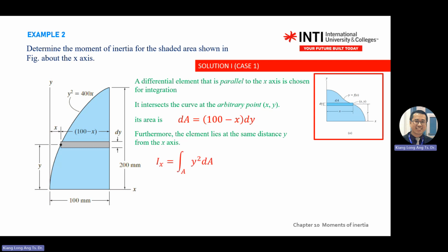Then you write Ix, this formula, Ix equal to the integral of y squared dA. Then you modify it a little bit. So this is Ix, from the x-axis. Y is here to here. So y squared dA, where dA is the area that you found on the top here. Substitute there.